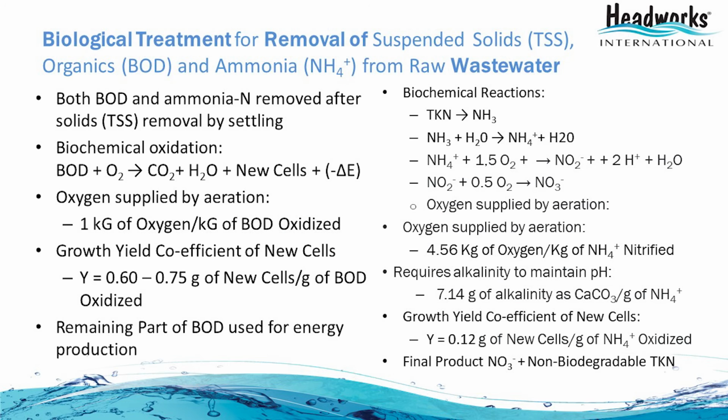This slide shows the chemical reactions. The BOD oxidation that I just mentioned is the basic chemical reaction. BOD represents organic compounds that are present in wastewater, and that is oxidized by oxygen, and oxygen is supplied in the form of air by aeration. And BOD oxidation reaction produces carbon dioxide, water, and then it also creates new cells.